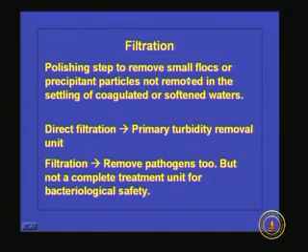So that's what I have written here. Filtration is a polishing step to remove small flocs or precipitant particles not removed in the settling of coagulated or softened waters. Because if the flocs are remaining there, it will not be aesthetically appealing. So the major objective of filtration is to improve the aesthetics of the water.